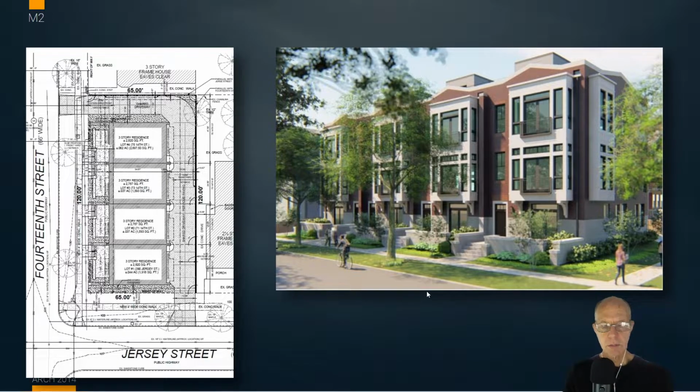So a site plan, this is an example of a project we're going to do. We're going to make this townhouse with these nice patios and all this vegetation around it. And this is the site plan for that. It's not intended to be graphically rich as far as for a presentation, but technically rich. It tells everything somebody needs to know about how far it sits away from the edges of the lot, how large the lot is that it's being placed on, what streets it's located at, ideas of where the sidewalks are located, all kinds of information that would be involved in helping to establish an approval to build this building.